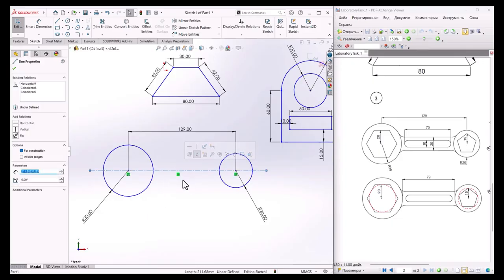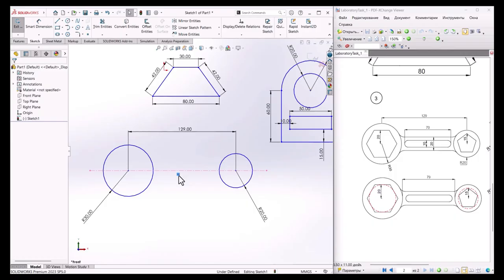And what's the meaning of this minus? So that means horizontal feature, horizontal relation. Okay, so if you do not want it made horizontal, so just select it and delete it, so then that becomes free, okay, not ideally horizontal.